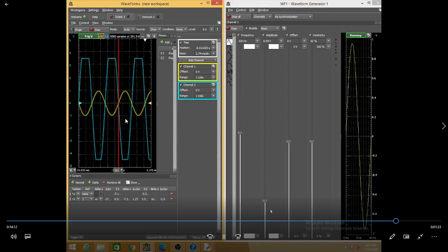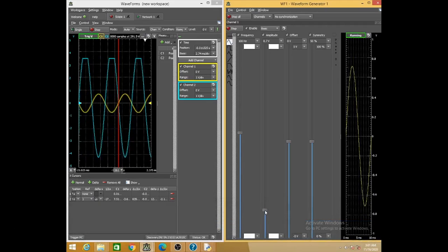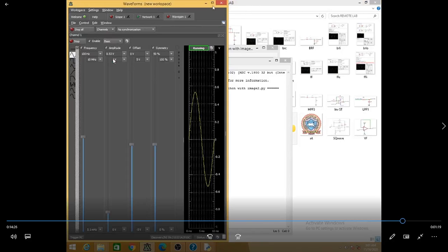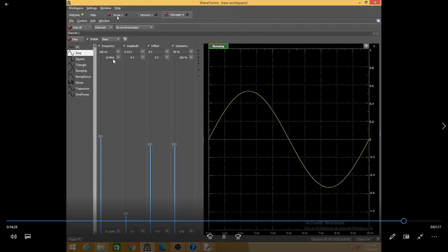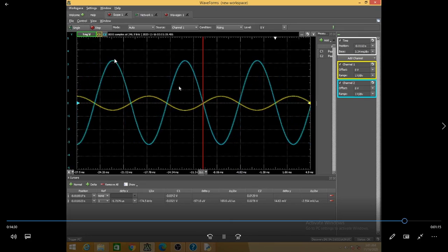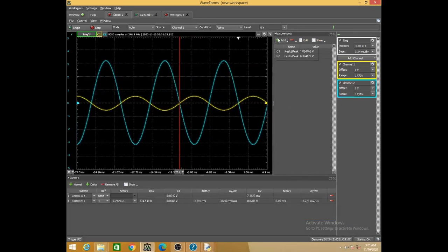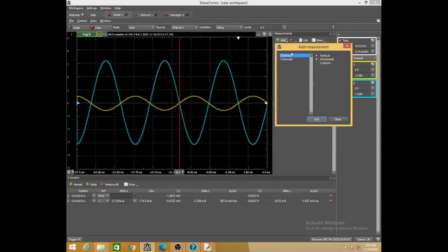You cannot measure here, of course, this happens to be your maximum output voltage. That is the saturation voltage. So you should never get this clipped-off waveform at the time of measuring the gain of the amplifier. While measuring the gain of the amplifier, the output should be a pure sine. It should not be a clipped waveform. Neither the positive half nor the negative half should be clipped.